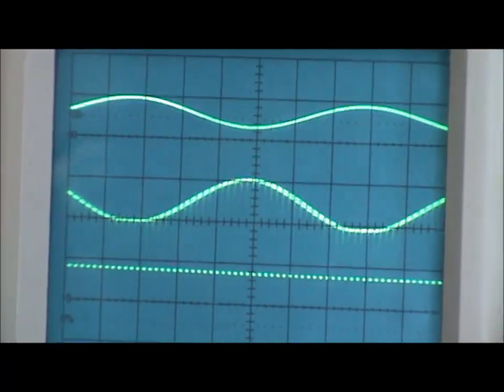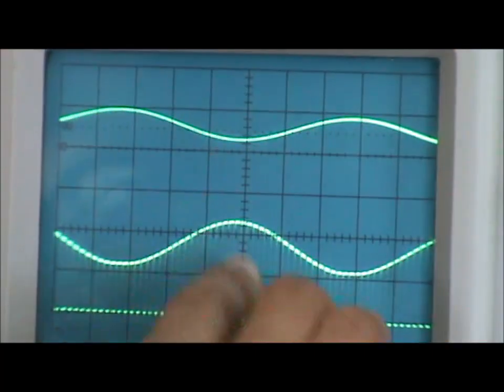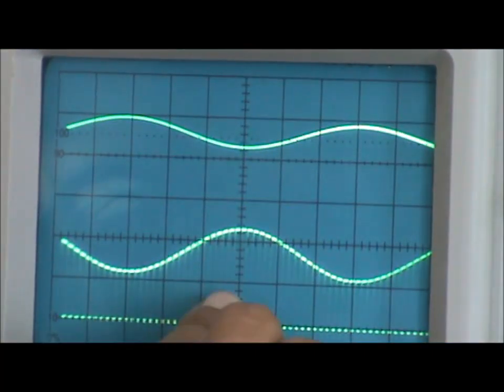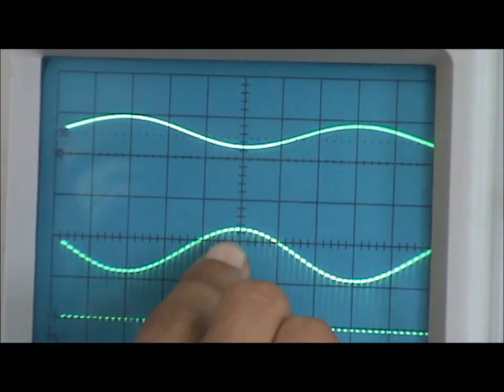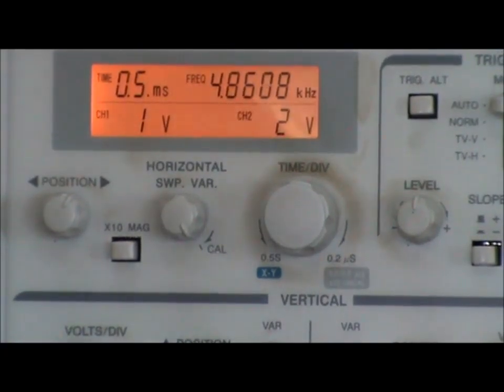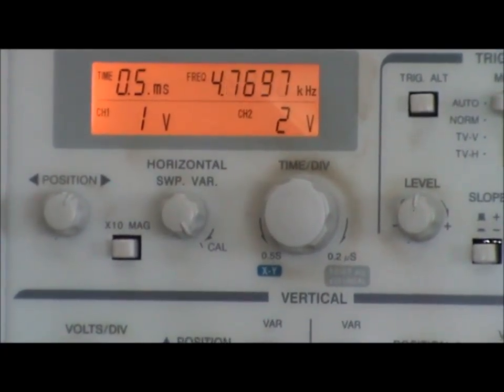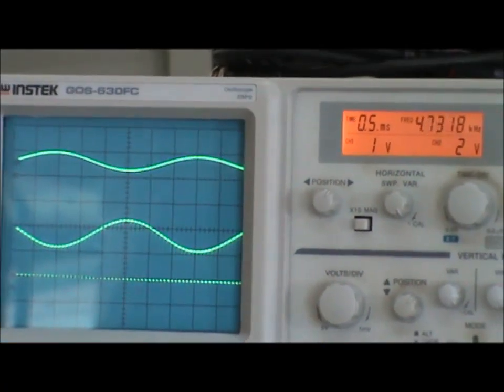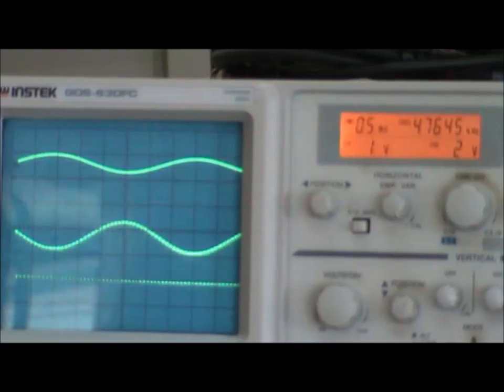Now you can measure from this line to this line, which will give you the maximum point. So it is 2.4 and 2. So Vmax will be 2.4 into the channel 2, that is 2, which will give you 4.8.